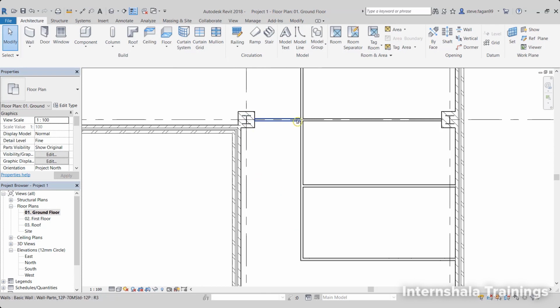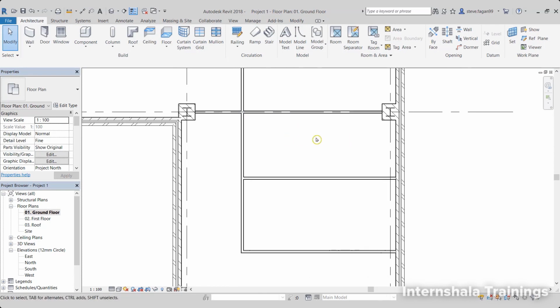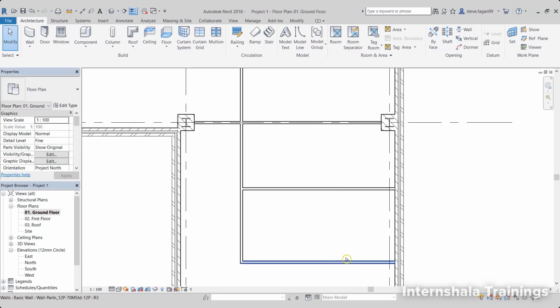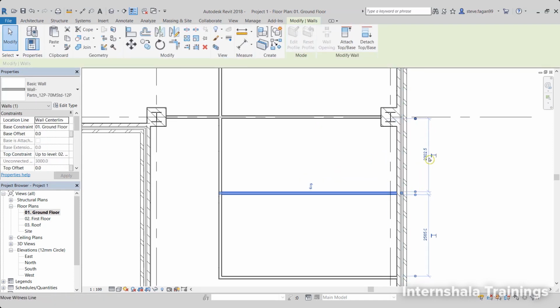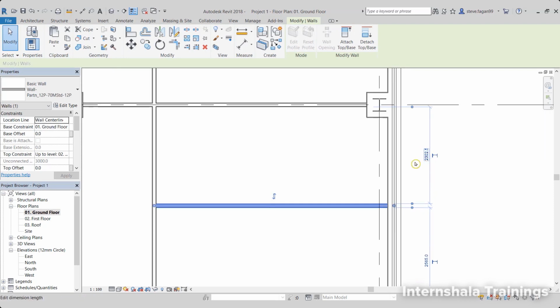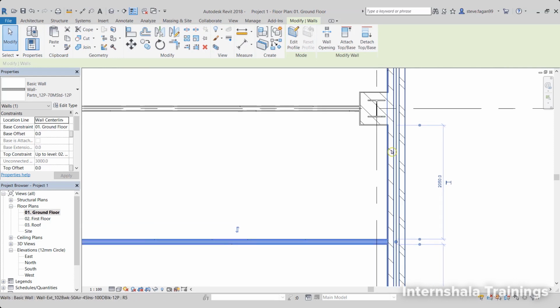So this wall here is at the center point, same here. And so these walls here are 2000 down. If I select my middle wall, you can see my temporary dimension is 2302.5. If your temporary dimension is snapping to the column like so, we can adjust its position. With that blue grip, I'll click, drag and move it up to the face of the plasterboard and let go. Now I can change the text to 2000.